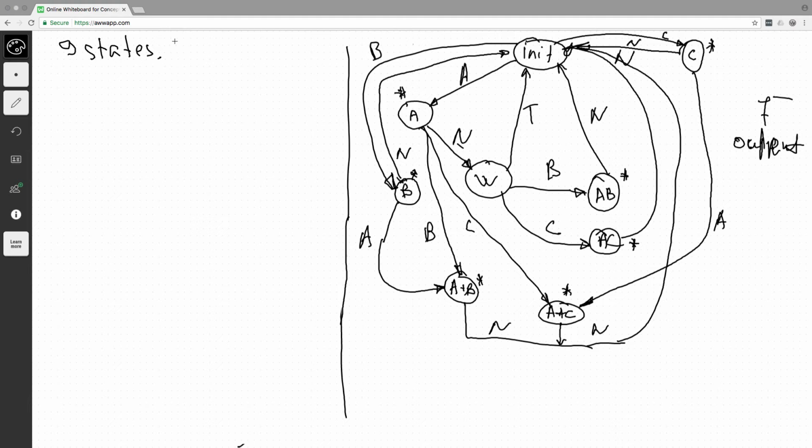9 states requires 4 bits of data. 4 bits of storage to memorize the state. I know this because if you calculate logarithm of 9 base 2 and perform the floor operation, you will get number 3. We want to round it up. So in other words, 2 raised to the power of 3 is just 8, and it is less than the required 9 states.